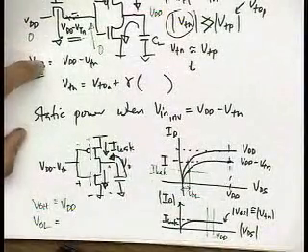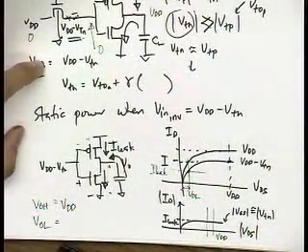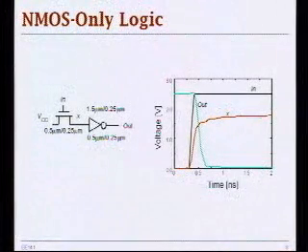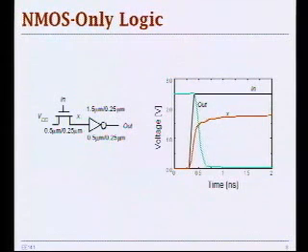If you look at the slides, you can see if you have a pass transistor driving an inverter, then node X, the one you see in red, would not be able to make it all the way up to VDD, but it will be at VDD minus VTH. And notice that the output, the green curve, would be somewhat delayed. And you have this small green bump here.